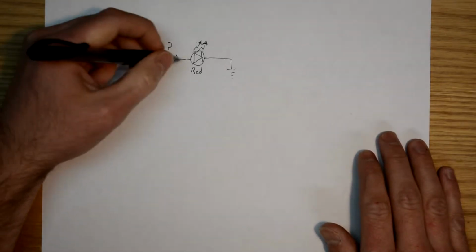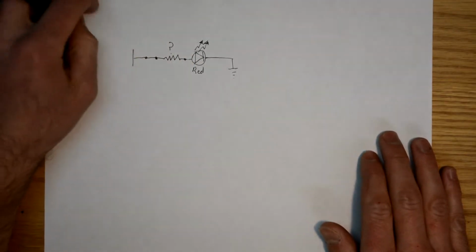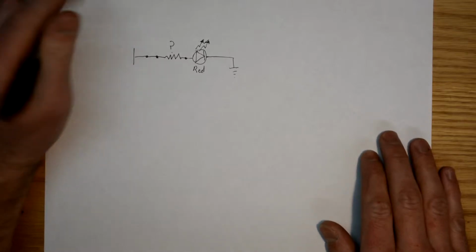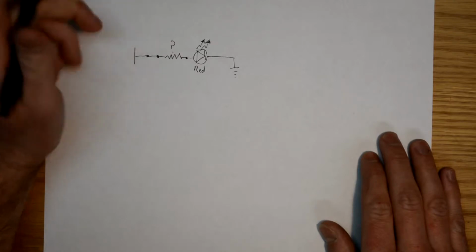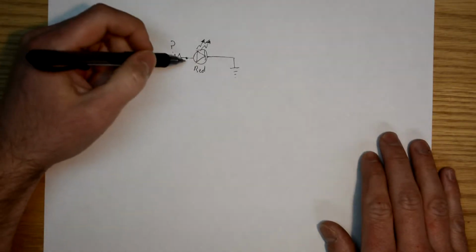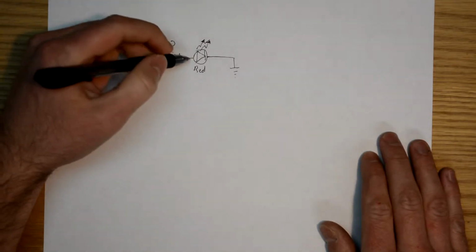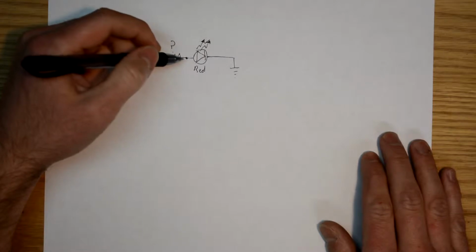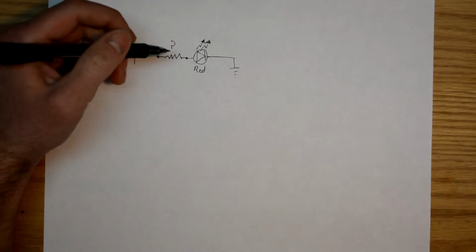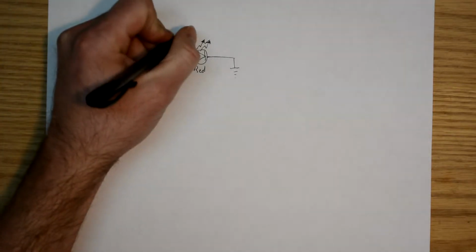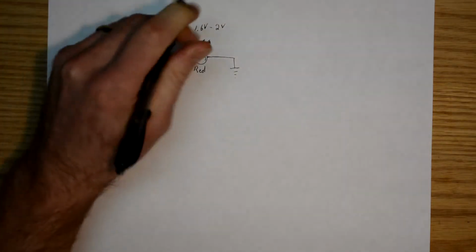I had him do a voltage test in this neighborhood, just trying to find the forward voltage drop of this LED, and he got, I think he said, a half a volt. I was kind of perplexed by that for a minute, but then I thought, oh well, it must be that this is doing some kind of multiplexing, so this is sending a PWM signal to this red LED. That's something like a 30 or 25% duty cycle, because a real LED should be in the 1.6 volts to 2 volt neighborhood.